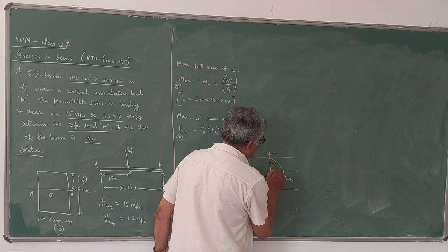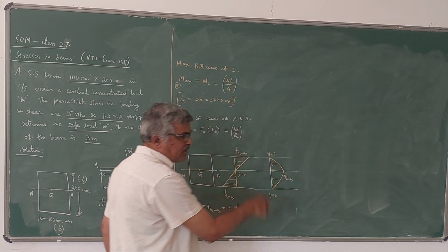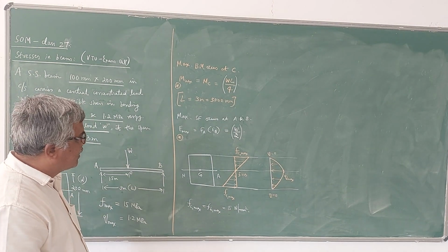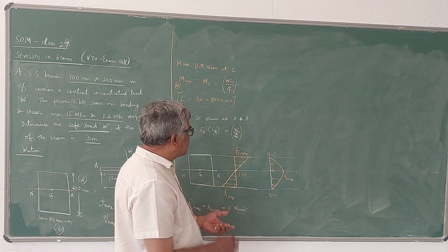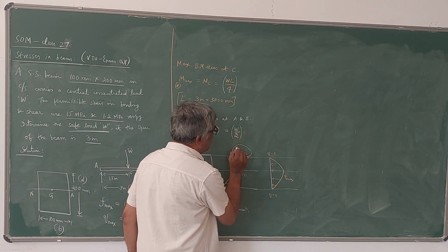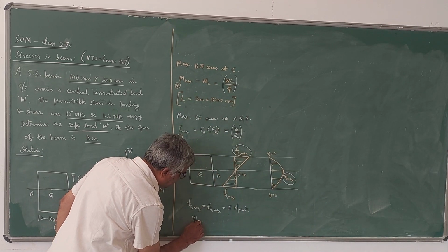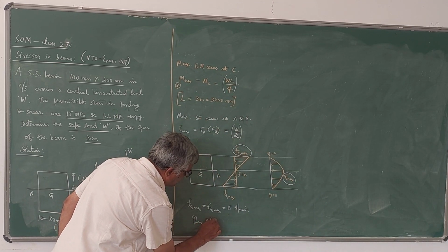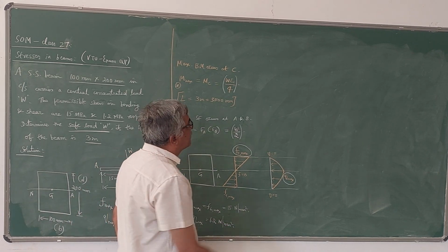So you know that at the neutral axis level we have the maximum shear stress. At the neutral axis level we have the 0 bending stress. So that means these two things we have to make use of now. This value and this value. Of course, here he has given the Q max value as 1.2. It should not exceed 1.2 Newton per mm square.